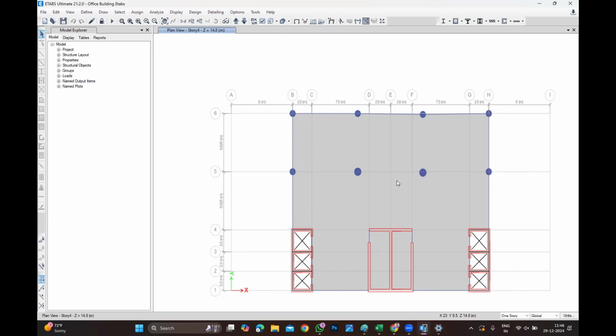90%. What happens in that case? By default it has to be here. Then the rest, others, could be a column or a shear wall. So automatically it falls under a dual system. You are not forced to keep the dual system; automatically you end up with it. But when the building is slender, when the building footprint is small, then the frame or dual system does not work. Then you have to go for shear wall.